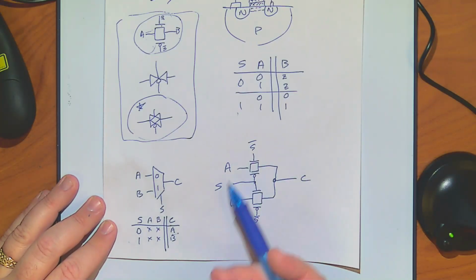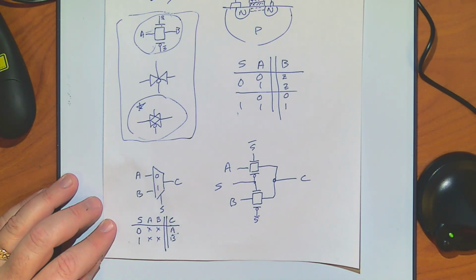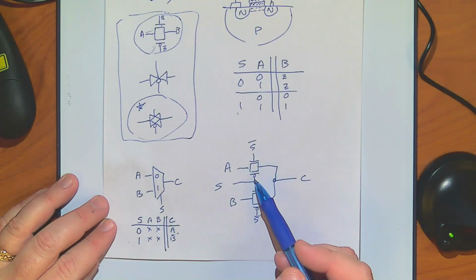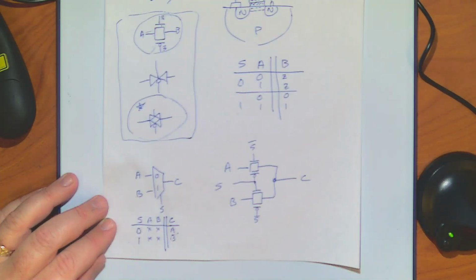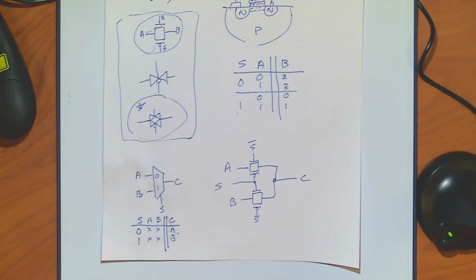So it's true. I mean, that's a mux right there. I'm able to build a mux with 4 gates. If you want the inverter for S in addition, because you don't have S bar available, sometimes you do, you can get away with 4. If you need it, an inverter is only 2 gates. That's how we were able to build it with our static logic. That's trivial. So I can build this with either 4 or 6 gates, depending on whether S bar is also available.